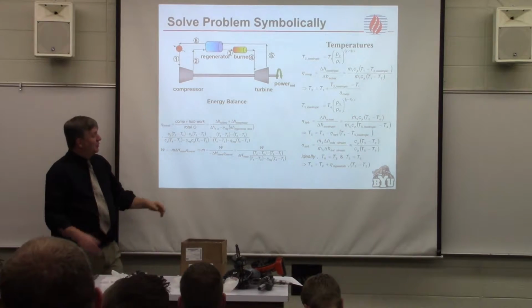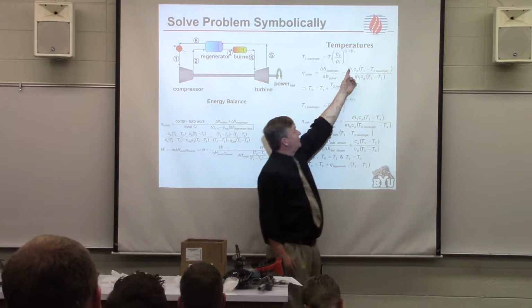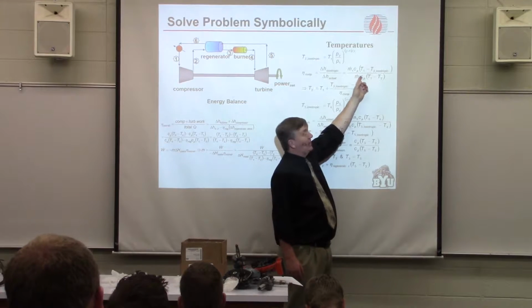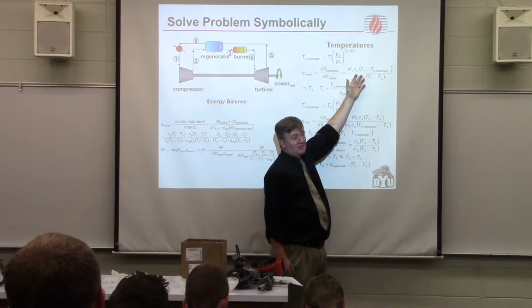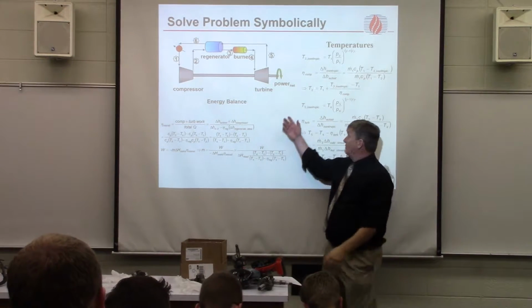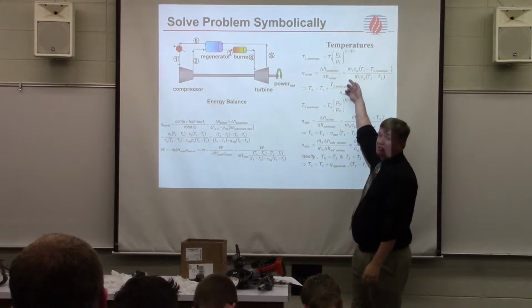If you wanted to do this more rigorously, you would not cancel, you would recognize the heat capacities are going to be different in the incoming and outgoing streams. So you wouldn't get as simple an expression for T5, but we still have these heat capacities.